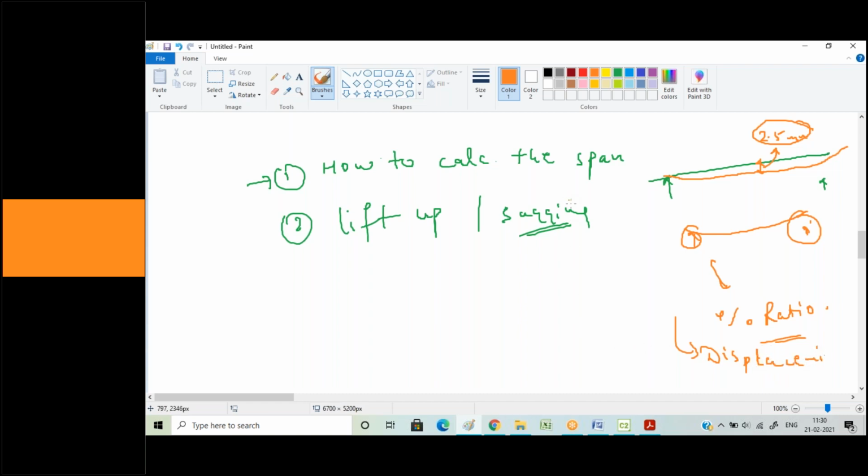So you get the maximum displacement, say, wherever the pipe is falling down, you get the maximum displacement. And if it's a problem, if it's above 2.5 mm or even at 2.5 mm, you can always shift your support.